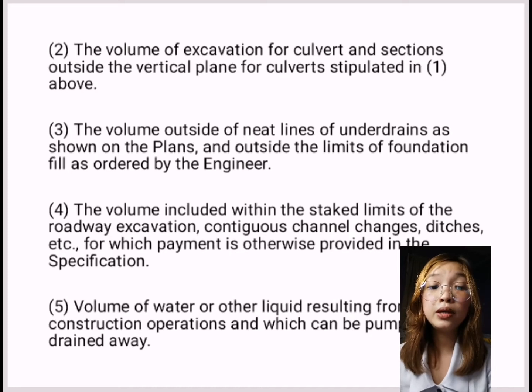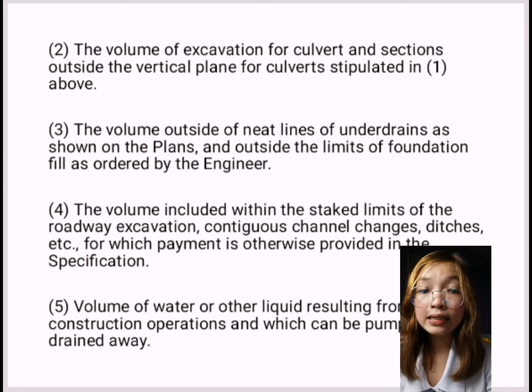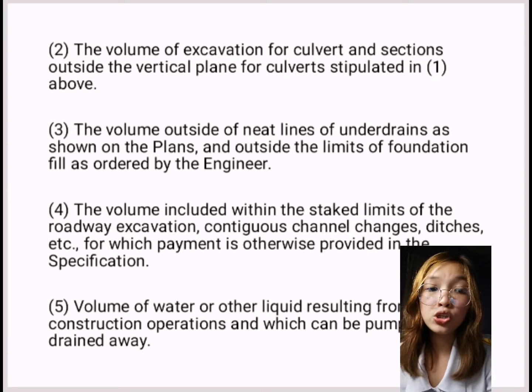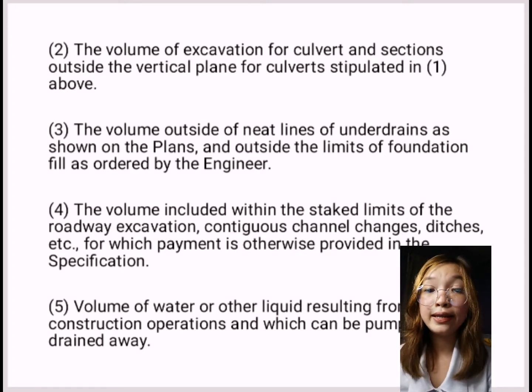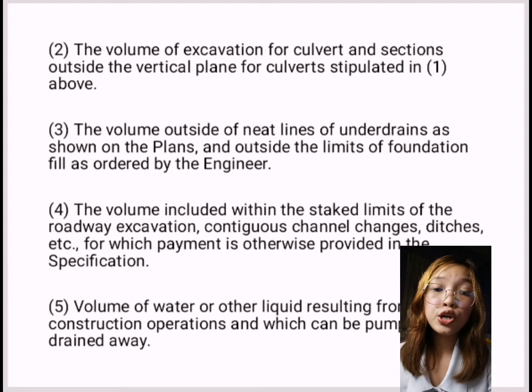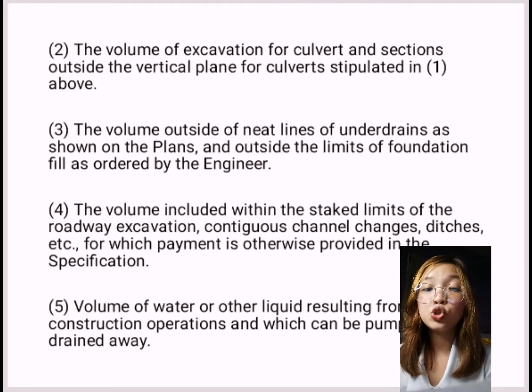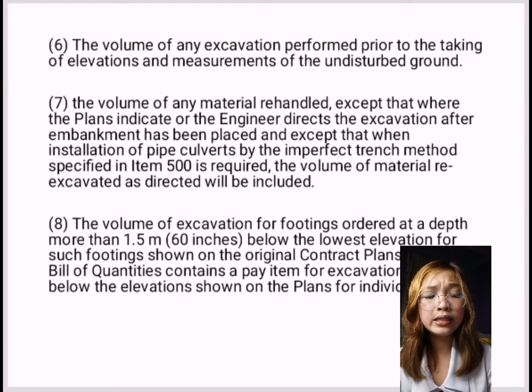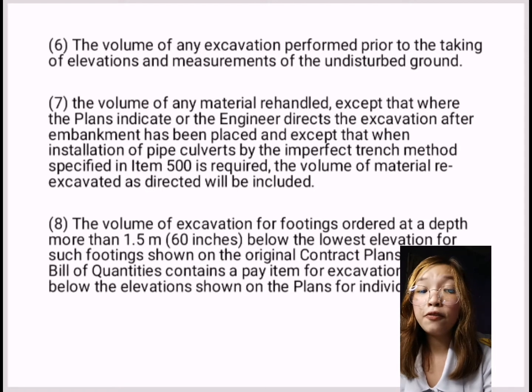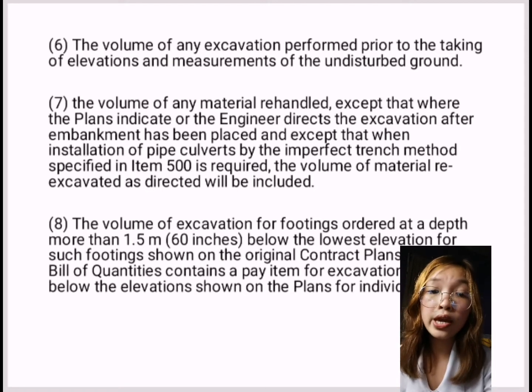Fourth is the volume included within the stake limits of the roadway excavation, contiguous channel changes, ditches, etc., for which payment is otherwise provided in the specification. Fifth is the volume of water or other liquid resulting from construction operations and which can be pumped or drained away.